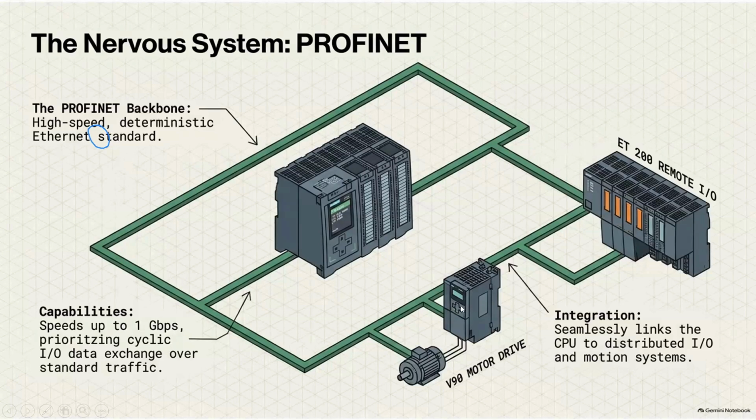So for these VFDs, there won't be Profinet all the time. Profinet might not be preferred. In these cases, Profibus will be used, wherein the Profibus communication will be given to the nearby IO module, and this IO module converts the Profibus connection and transfers it to the main PLC through a Profinet connection.